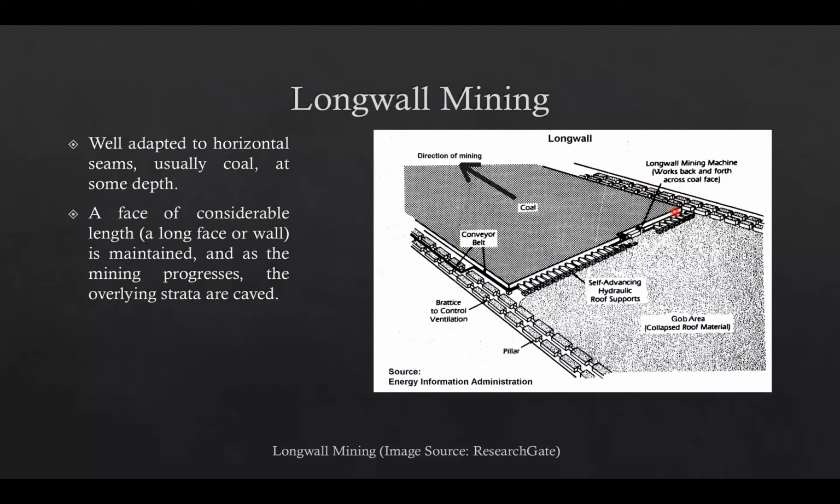And then we have this long face here, the longwall, and we have these hydraulic supports mostly to provide a safe working environment. And then we have this longwall mining machine that cuts the coal. So the coal is then transported through these back conveyors. And behind these hydraulic supports, this rock material is caved in and the surface subsides downwards.